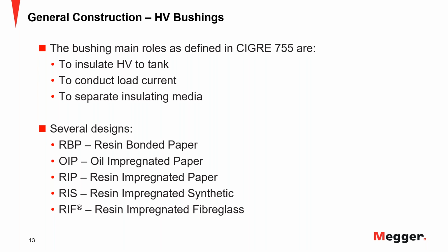And in these different designs, I think that historically, we can look into the construction, of course. The first ones were very solid insulation manufactured for lower voltages. But as the voltages were increasing in the system, right, the type of insulation system for bushings was also being developed and evolved.